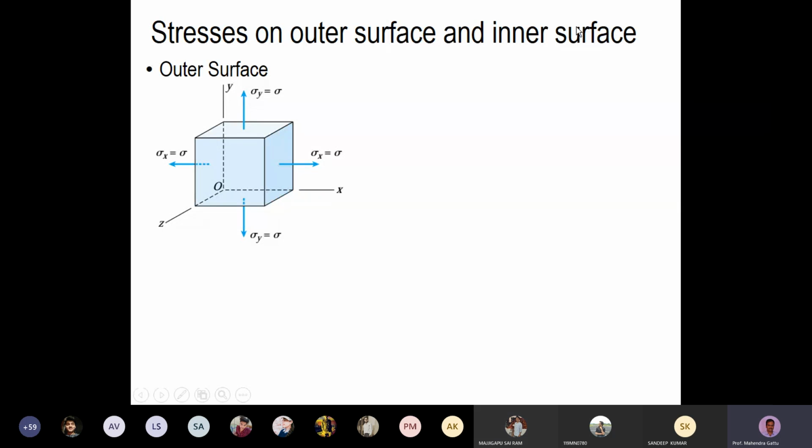So, what is happening here on the left face and the top face, or right face and the top face? We have sigma comma 0 on the right face, and the top face is also sigma comma 0. So points M and N on the sigma theta tau theta axis are coinciding. Okay, so we cannot draw a Mohr circle there. For this specific case, we don't have a Mohr circle. We just have a single point for the in-plane stresses.